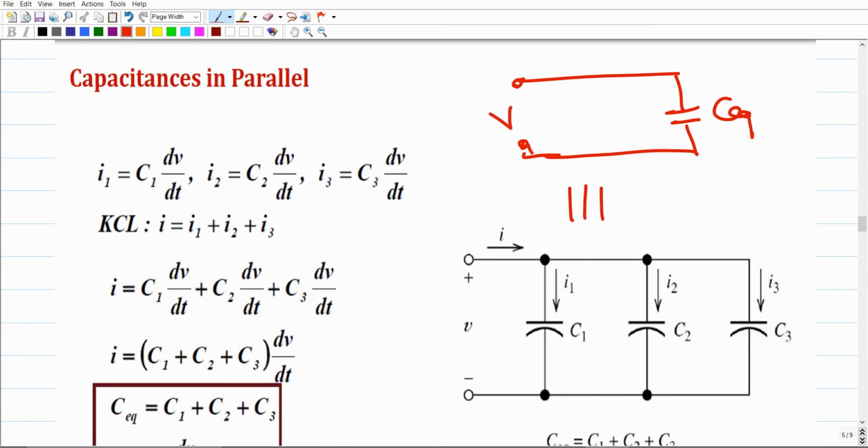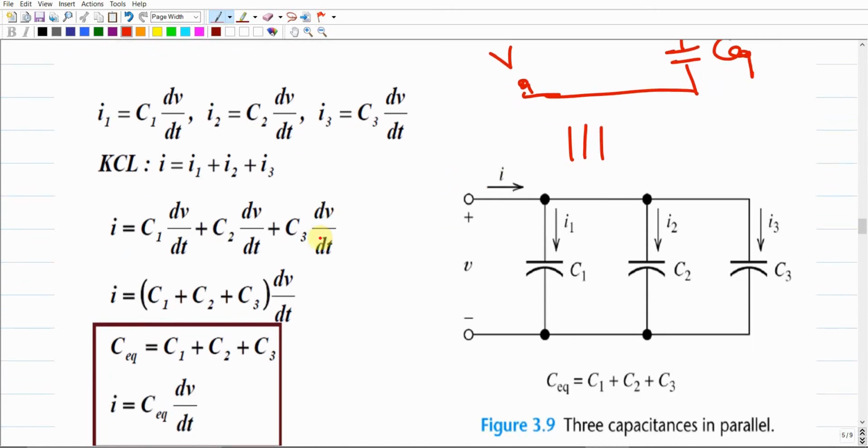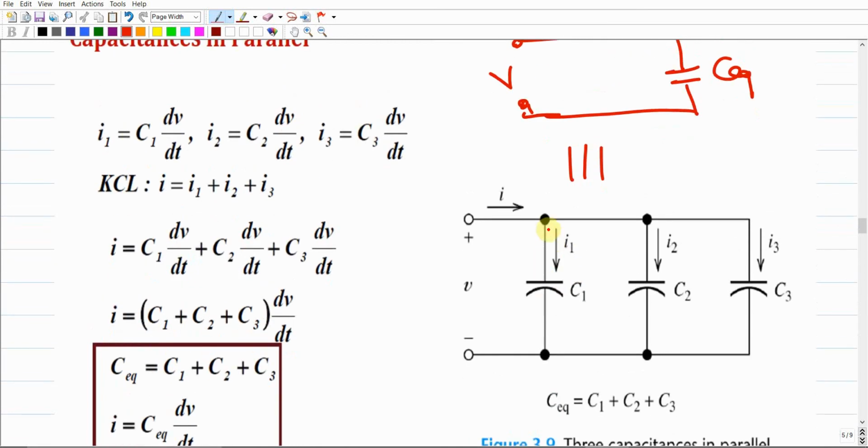This is typically the same thing that we did before for the equivalent resistance. Like you have a set of resistors in parallel, and we would like to end up with the equivalent resistance. So if we apply Kirchhoff's current law at these different nodes, node 1 and node 2, you're going to realize that the voltage over this branch should equal the voltage over this branch, and should equal V, the total voltage that comes from the source, since they are parallel.